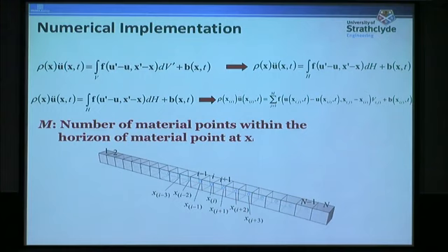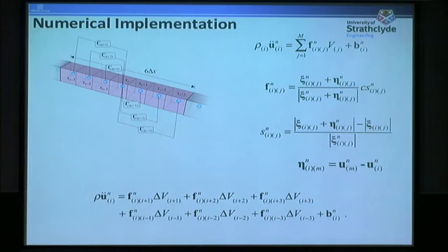What we are basically doing is discretizing our domain into finite volumes, and we insert a point at the center to represent each volume, so that we can convert our integrals to a summation. For those of you who are familiar with molecular dynamics, it has a very similar equation. But as I said, this is a continuum formulation.